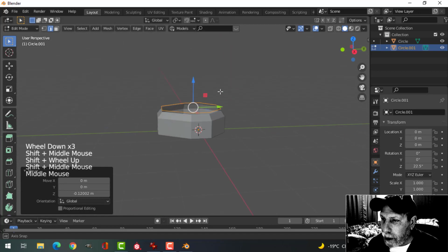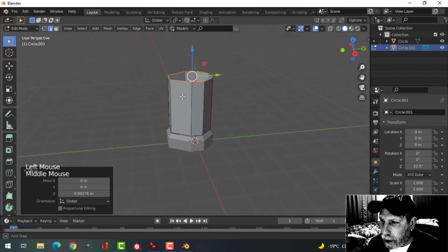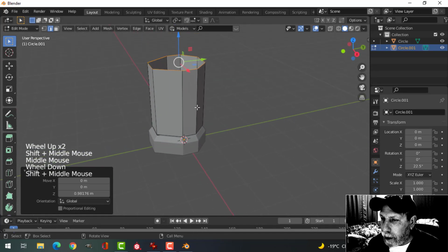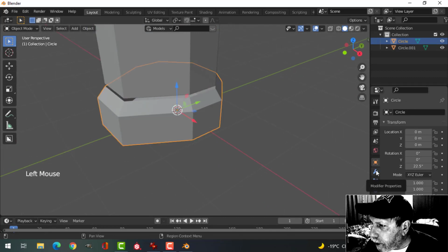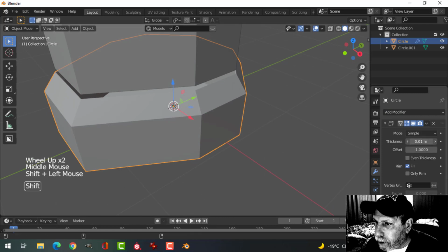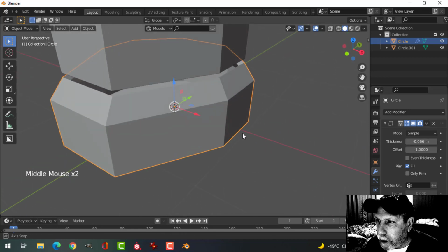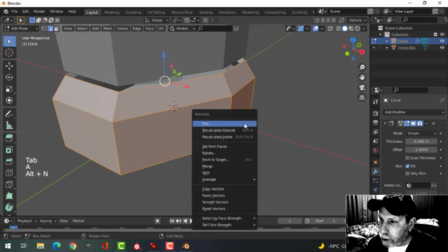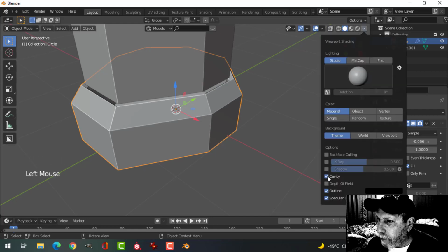So let's just extrude this up a ways like that, and then let's start thinking about, I might put on solidify. Trouble seeing this, and I want to make sure my polys are going the right way. I'm going to go ahead and turn on the cavity shader.